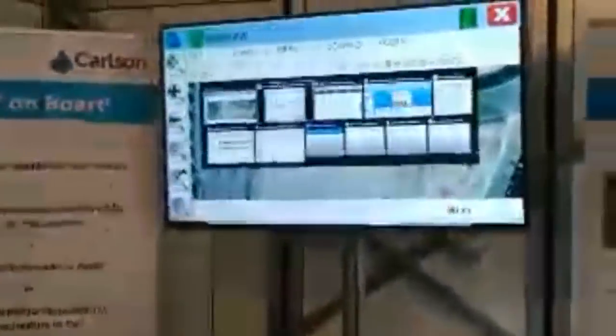Now, let me show you the results of this resection. This is a screen picture. You see the standard deviation, this is the closure of the resection. Northern, eastern coordinates in meters, say 2 millimeters, 1 millimeter. RMS. Elevation is a bit higher because it's GPS, we cannot improve that in the resection.